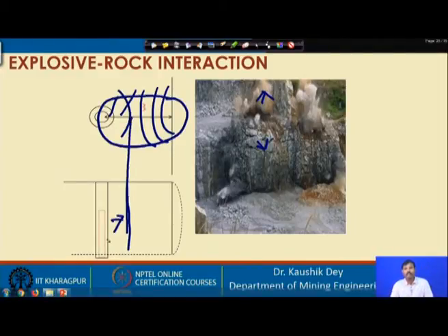So, basically this is the utilization of the time gap between the shock energy release and the gas energy release. By understanding the energy transferred from the explosive to the rock from crater blasting experimentation, we are able to design a proper burden for our rock fragmentation.